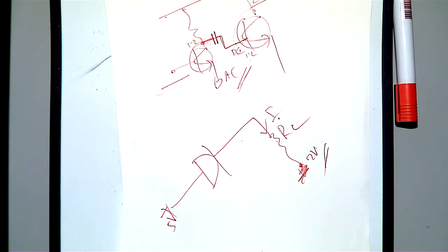Then in a practical power amplifier, this is a block level diagram. If you check a power amplifier, you have voltage amplification, again you got voltage amplification, then you will see some driver stage, then you got a power stage, then you got a speaker. So kind of like this. Maybe this is a multi-stage voltage amplification, then you got a power amplifier. Then sometimes in some circuits you will see a transformer instead of a resistor here. Then here you will be connecting your speaker.